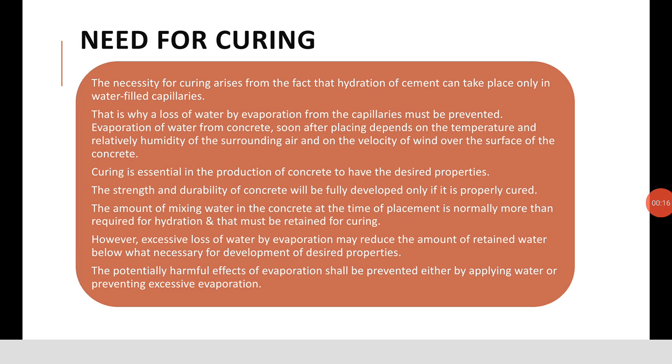Need for curing. The necessity for curing arises from the fact that hydration of the cement can take place only in water-filled capillaries. That is why a loss of water by evaporation from the capillaries must be prevented. Evaporation of the water from concrete soon after placing depends on the temperature and relative humidity of the surrounding air and on the velocity of wind over the surface of the concrete.